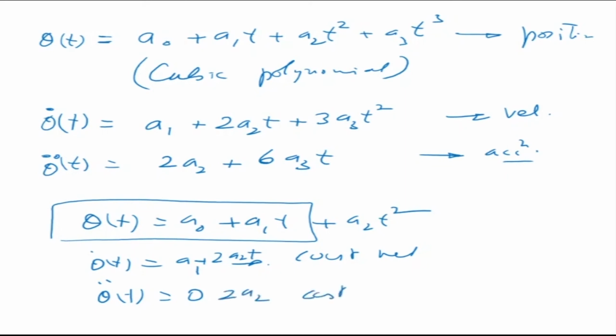This is a constant. Okay, now this is also not possible. Why? Because you know that when the joint is moving, it will have to accelerate, remain constant, and then it will have to decelerate again, like that. So neither can velocity be constant nor can acceleration be constant, and obviously neither of them can be 0. Okay, so it will vary as we move along.